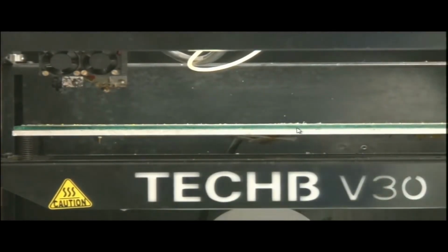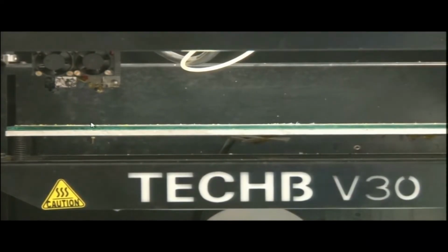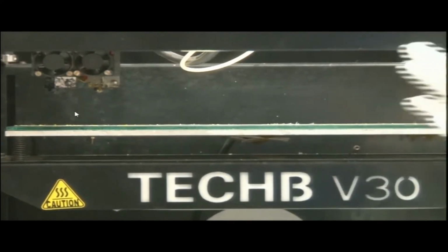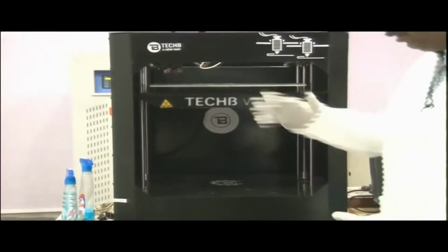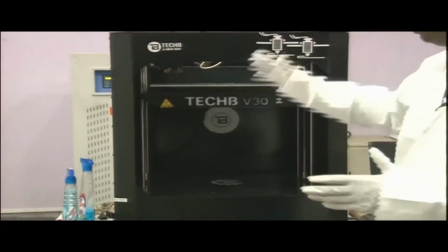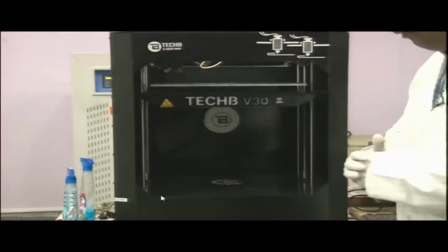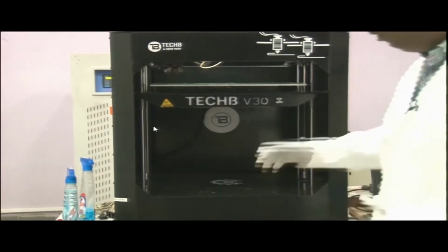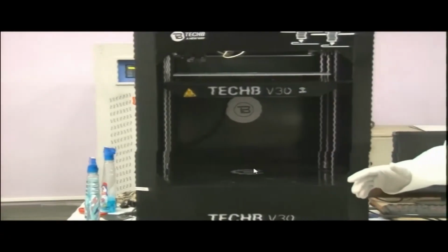It is heated to a specific temperature so that the material deposited here, which is at about 200 degrees, can stick and set easily. We have to deposit one layer upon another during fabrication. Whatever we want to fabricate here in FDM technology, the machine size is 1 foot by 1 foot by 1 foot. So in XYZ directions, the envelope is 1 cubic foot.